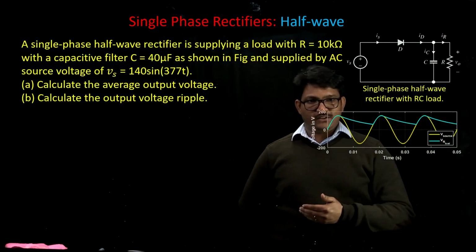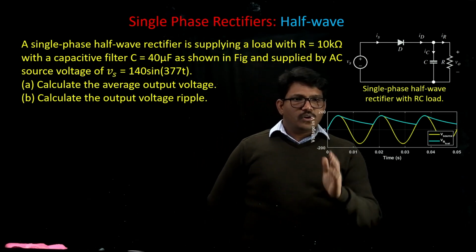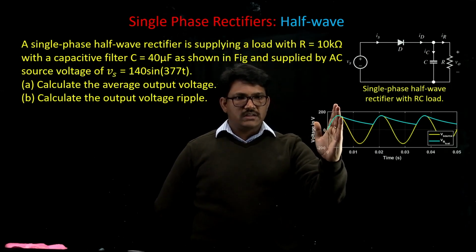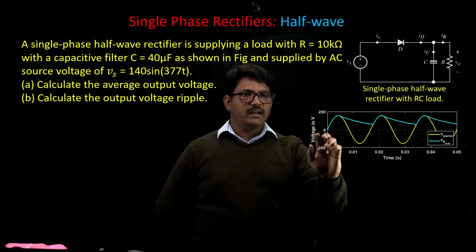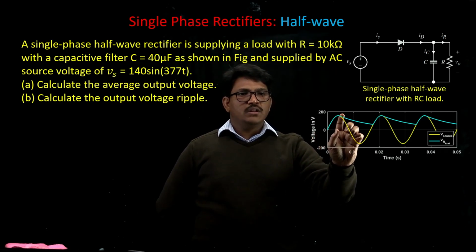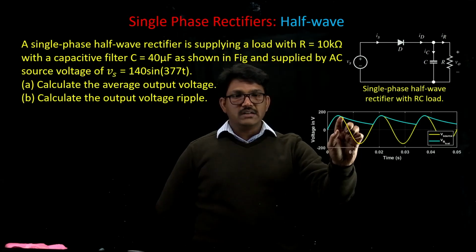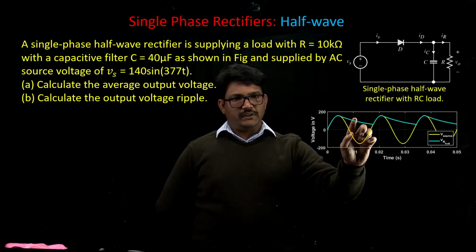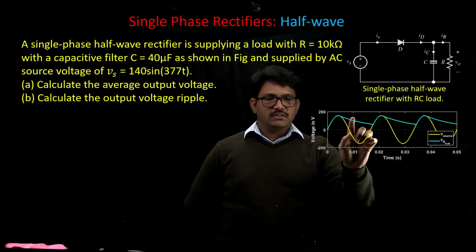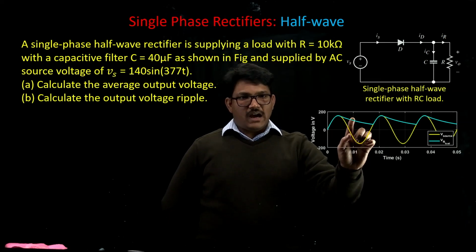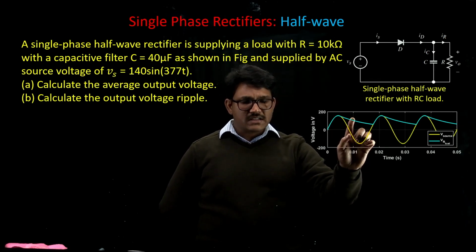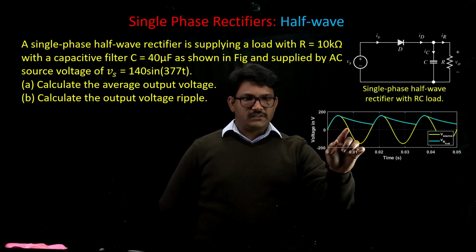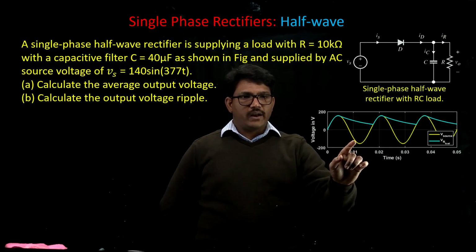the way we have in a resistive load, because if you look at in the beginning stage where the source voltage will be higher than the load voltage, that is when you will have diode conducting and the capacitor starts charging. The moment the capacitor charges to the maximum voltage, then your source voltage is reducing, but the capacitor voltage will be slowly reducing because of its opposition to the sudden changes in the voltages or the charge in the capacitor. So due to charge in the capacitor, the voltage across the capacitor is going slow, whereas the source voltage is now going low. That is when the diode will be off.